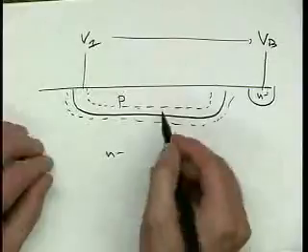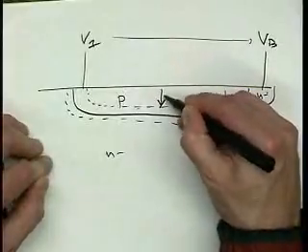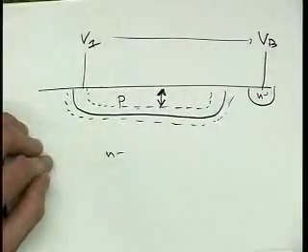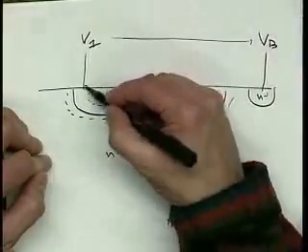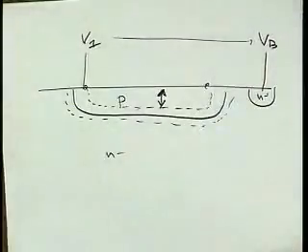this junction changes. Well, that means that the amount of material that's still available to carry the current from our resistor between here and here is changing too. Heck, if I make my resistor wider or narrower, of course the value is going to change. So this has got to have a voltage coefficient, and it's directly linked to this junction business here.